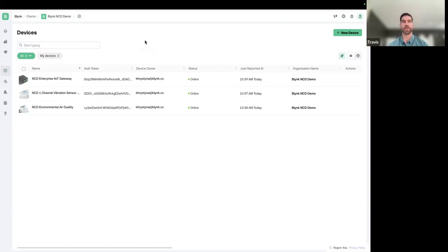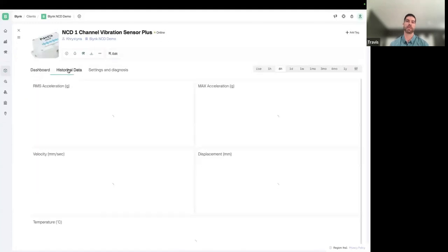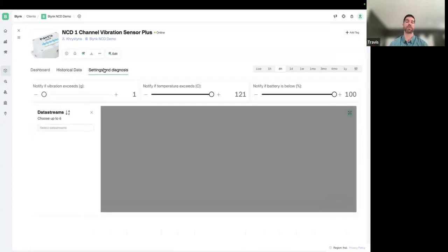Yeah, so the battery life is relevant to the user's configuration. Some of the sensors can be configured to report every 10 seconds. But for most users, the default configuration is that it reports about every 10 minutes. You can change that as needed for your application. The longer you have that interval, the longer the battery's going to last.